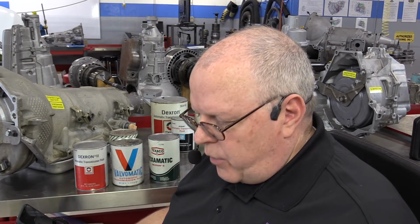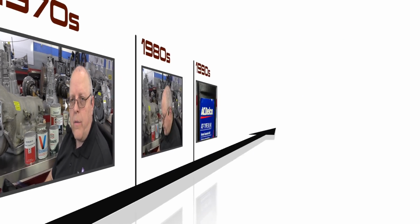So for the 1979 model year, General Motors released 2 transmissions with a torque converter clutch. They were existing versions of the Hydra-Matic 200 and the 250, but they put the letter C after their designation to indicate that it had a torque converter clutch. Now there were no computer controls involved, it was just simply pressure switches and a brake switch involved in activating and deactivating the torque converter clutch.